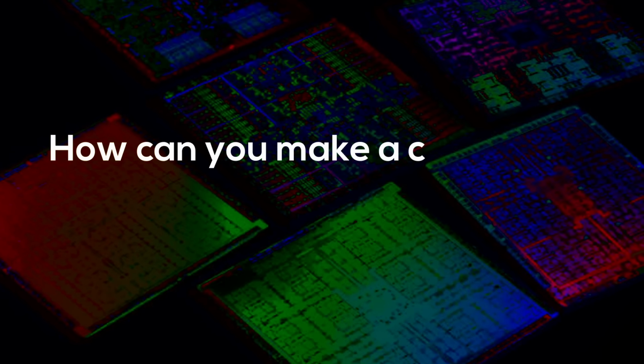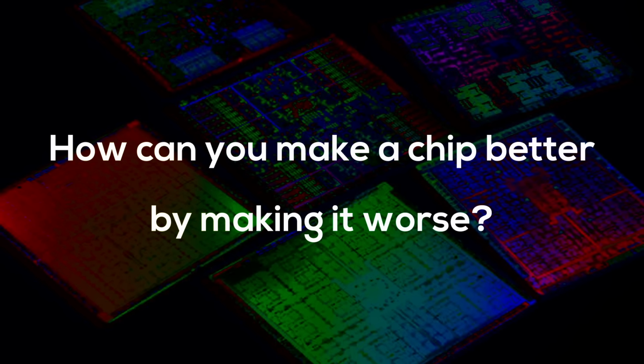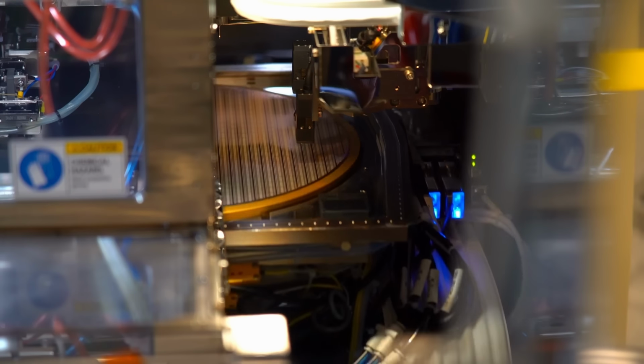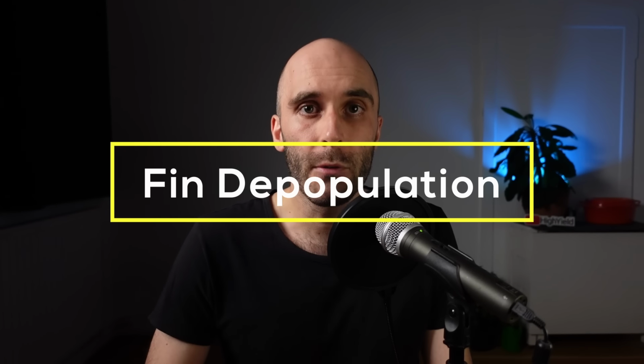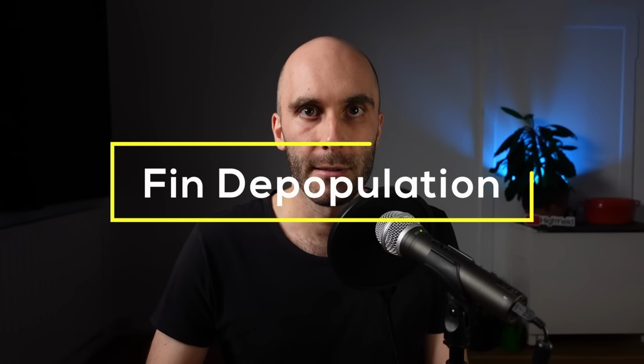How can you make a chip better by making it worse? It has to do with the height of transistors, the height of cells, and the question, how can we continue to scale chips when transistors just don't get smaller anymore? A special technique called Fin Depopulation is one of the reasons why modern chips still continue to scale, even though new process nodes struggle to keep up with Moore's law.